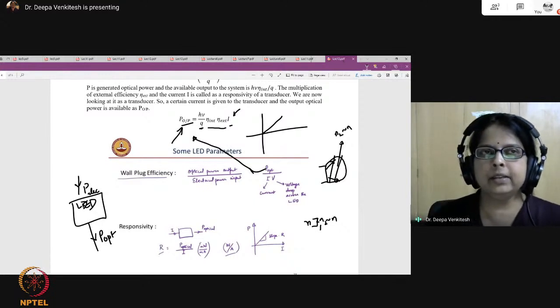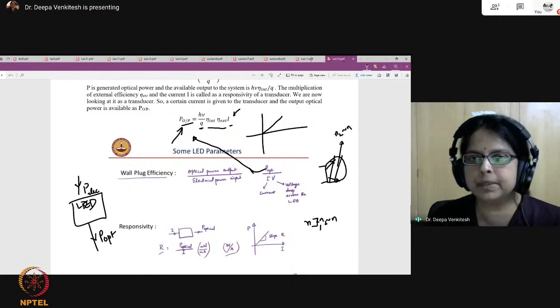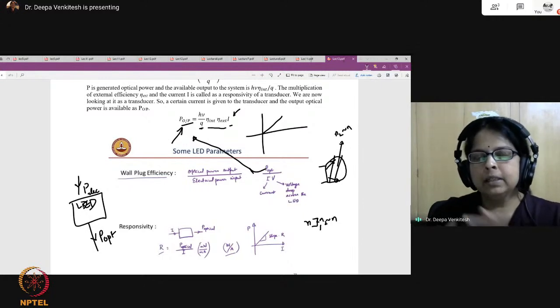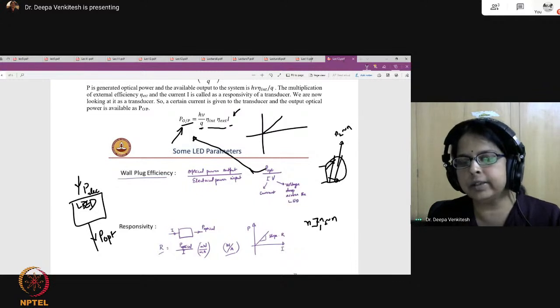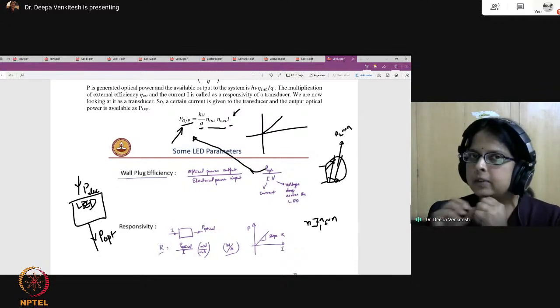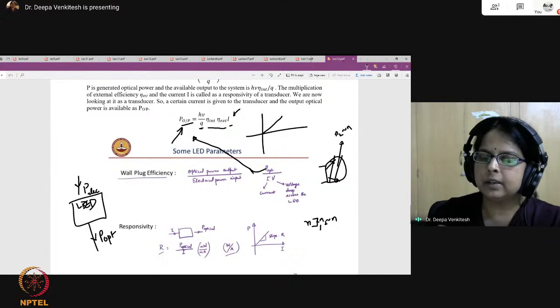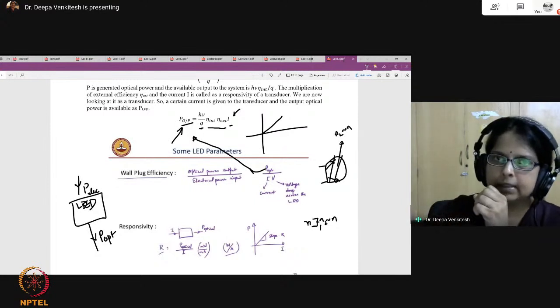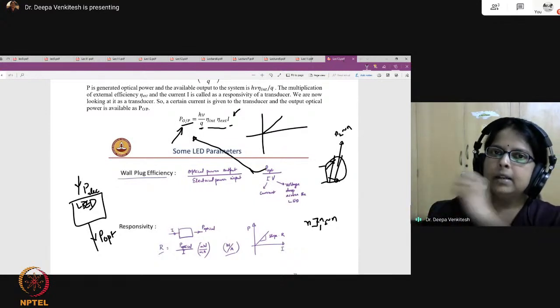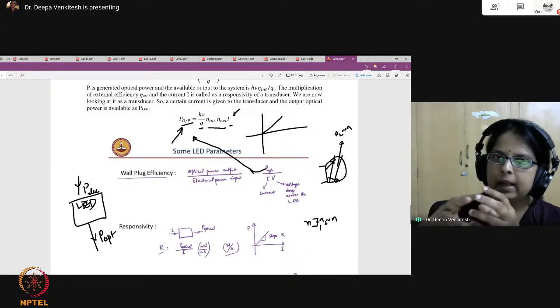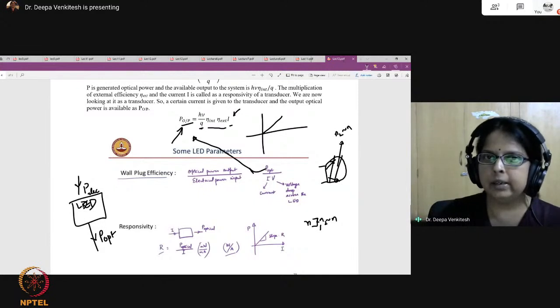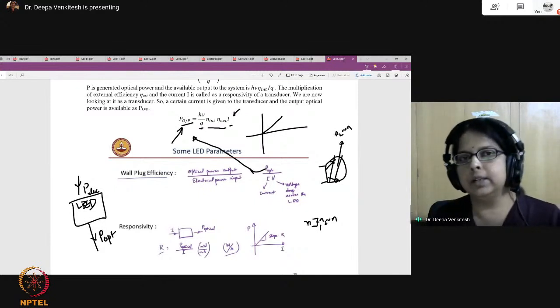It's like what happens in a prism. You send white light through the prism, and it splits into different colors because the refractive index for each color is different. The speed for each color is different. The same thing happens in a fiber. Some colors arrive faster, and some arrive slower. So the same information now arrives over a spread duration of time, and that's not a good idea. We'll talk more about it.